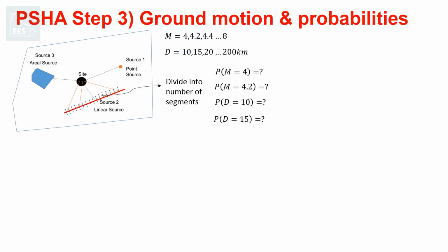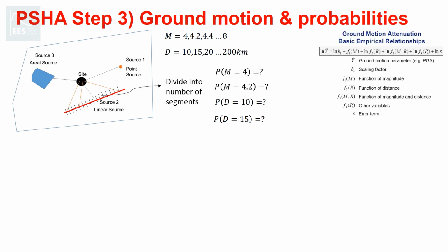One thing interesting in the estimation of seismic hazards is that there are equations available that calculate the PGA given the magnitude and distance. These empirical equations are called ground motion prediction equations, or GMPE. These are developed for the region where you conduct PSHA, and if not available there, then you can borrow from one that has similar tectonics. So given the distance and magnitude, we can calculate the corresponding PGA.